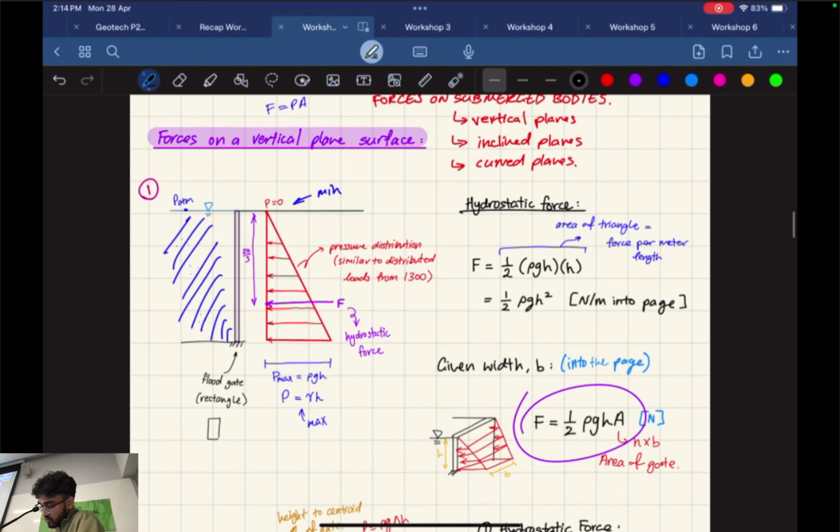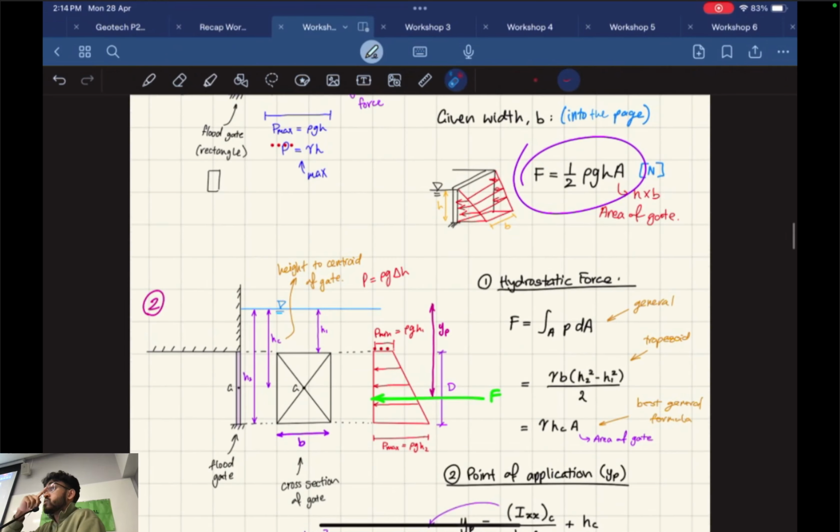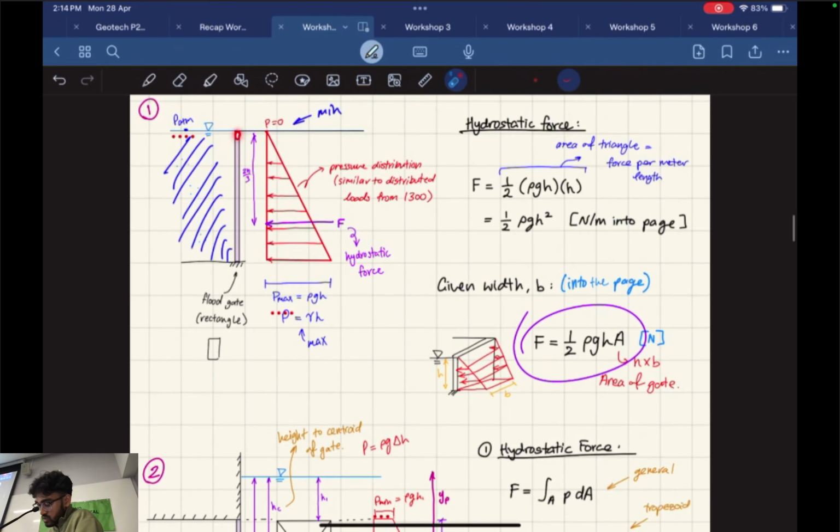here it is. So for vertical planes, I've drawn 2 different examples. One where all the water is going to be held by a gate. So in most of these questions, by the way, you have a gate and water on one side or even both sides, which is a question that I'm going to go through. Right? And that water, so let's say we've got water on this left side, is going to cause pressure or have some force acting on the gate. Alright? So it's going to be a triangular distributed load, which we saw in ENGG2500 for the civil engineering students. I mean, by environmental.